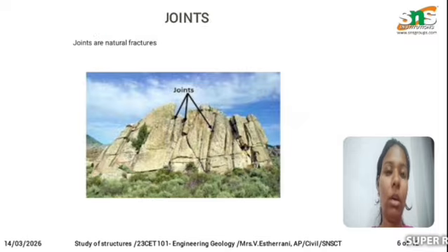These are the types of faults that we have seen. A fault is nothing but a fracture that is created in the rock surface. There are majorly three types of faults created in the rock surface. The first one is the normal fault, next is the reverse fault, and then the strike slip fault. A normal fault is created due to the tension force of the rock surface. Next one is the reverse fault or thrust fault. It is created due to the compressional force of the rock surface. This compressional force may be caused by external or internal movements or by tectonic plate movements of the rock surface.